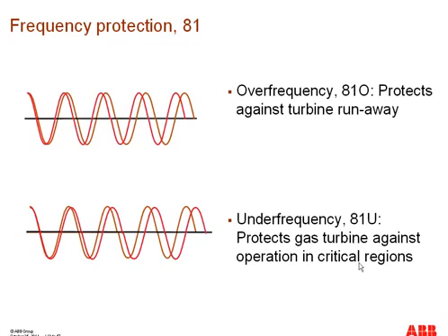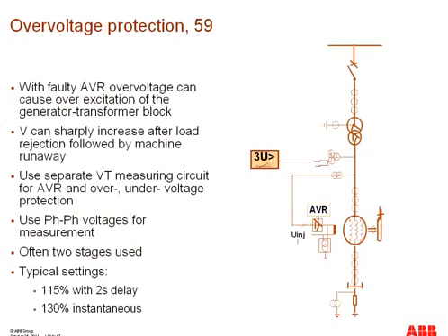The under frequency conditions prevail as a result of lack of generation in the network. The function can be used for load shedding schemes as well as for remedial action. And also, this function can be either definite time or a voltage magnitude dependent time delay, which means that the higher the voltage, the longer will be the time. This function is also supervised by an under voltage function and is blocked if the voltage is below the set threshold value.